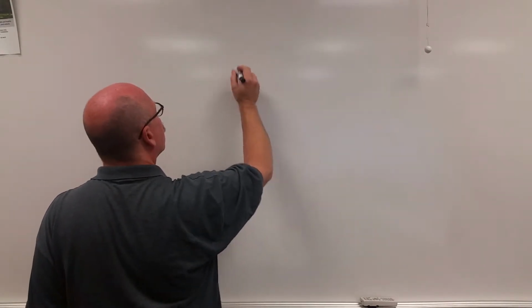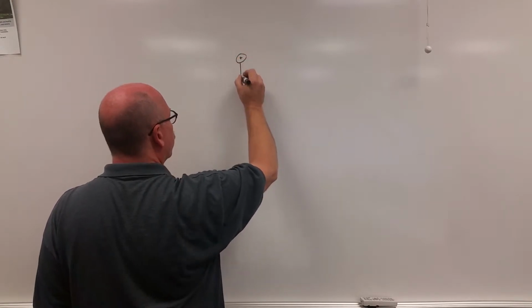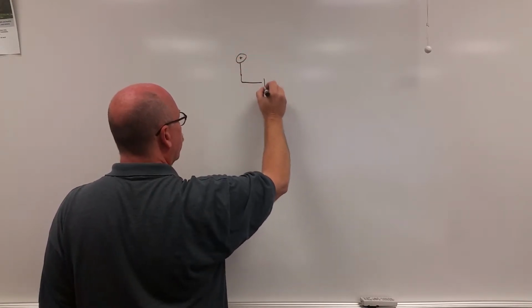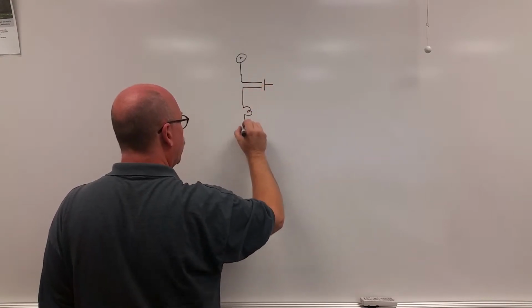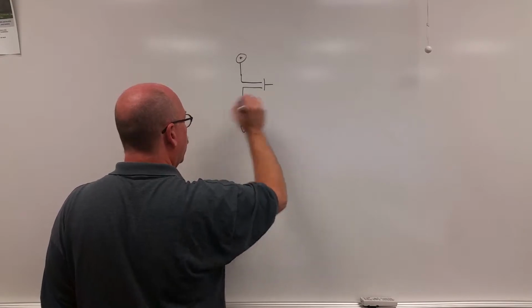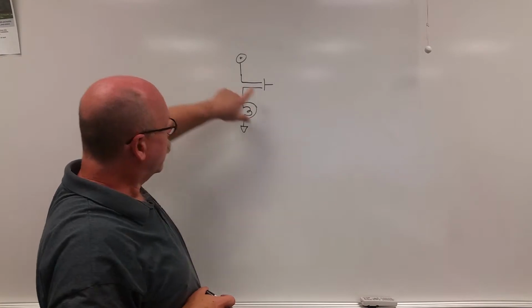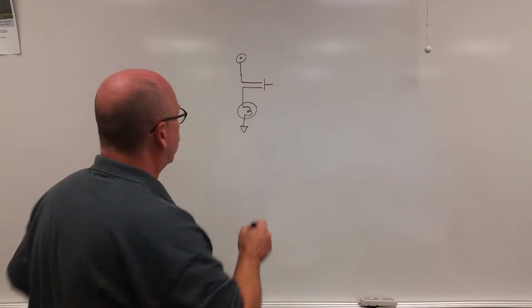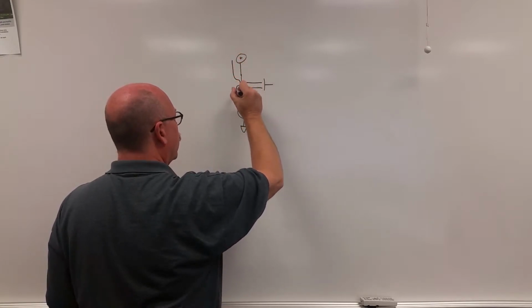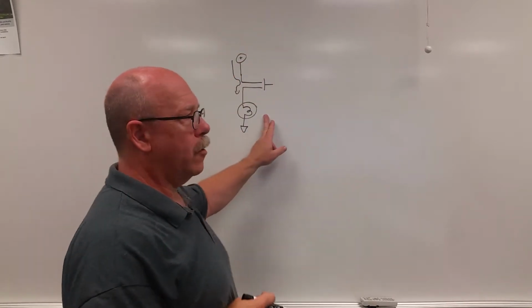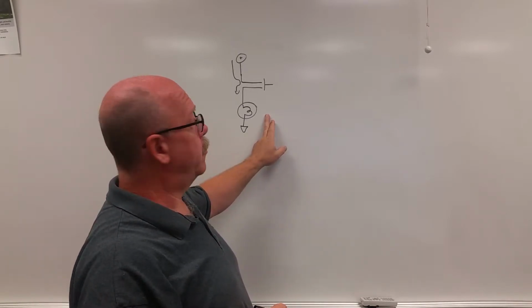Typically, when you source something, you have a positive voltage or a higher potential voltage that will drive through, let's say, a switch, and we'll go to a light bulb. In this particular instance, the light bulb is going to ground. When I push the button in, the current will flow. We'll do conventional, from the positive to the negative through the bulb and make the bulb light. I am sourcing potential to the bulb.